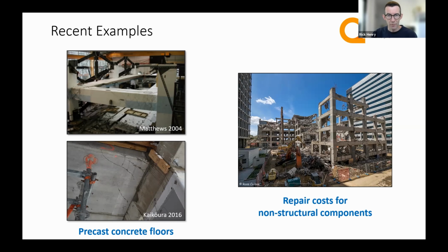But when we consider their response in an entire system, particularly when they act as a diaphragm for seismic demands, and when they're working together with the seismic system, perhaps a moment resisting frame that surrounds them, the interactions and the deformations that are occurring can cause quite a lot of damage to the floor units themselves. And that's often demands and loads that are well above what we may have considered them to be designed for in the first place.